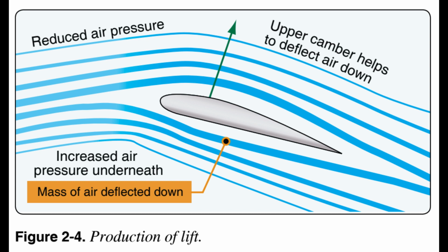The lift generated by an airfoil depends on such factors as: 1. Speed of the airflow. 2. Density of the air. 3. Total area of the segment or airfoil. 4. Angle of attack, AOA, between the air and the airfoil. The AOA is the angle at which the airfoil meets the oncoming airflow, or vice versa. In the case of a helicopter, the object is the rotor blade, airfoil, and the fluid is the air. Lift is produced when a mass of air is deflected, and it always acts perpendicular to the resultant relative wind.